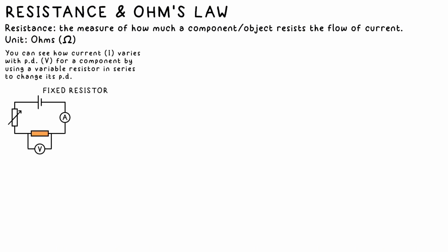If we make a circuit with a resistor and change the PD available to it, what we find is that an increasing PD results in a greater current flowing. In fact, doubling one doubles the other, so we can say that PD and current, or V and I, are directly proportional. Drawing a graph of these two makes a straight line, and if we turn the battery round, we can get negative values for both too, but still a straight line through the origin.